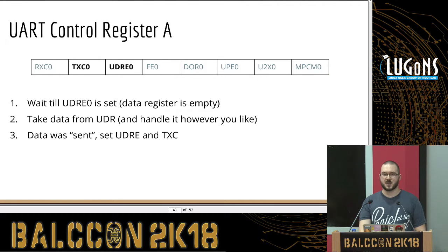You could essentially implement the whole emulator terminal on top of it and use the actual UART protocol to send the values. And once we've dealt with the data in the data register, we'll have to set the data register empty flag and the transmission complete flag. Of course, this isn't equivalent if you would actually implement the actual UART protocol. But since we're just dumping the values, we can treat the data register empty and the transmission complete as somewhat equivalent.